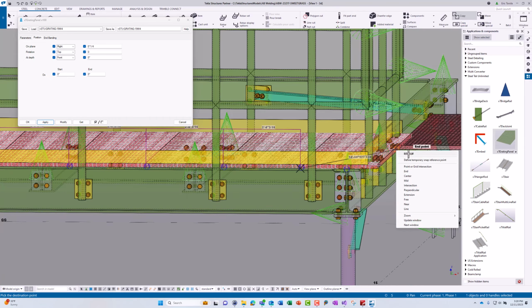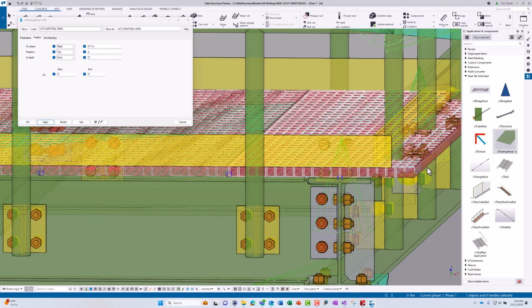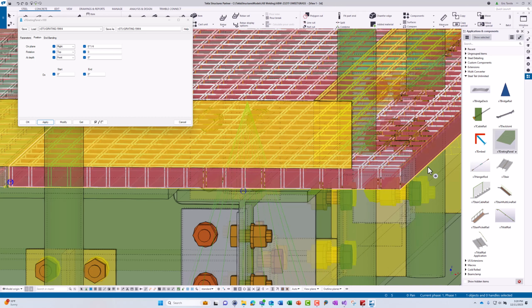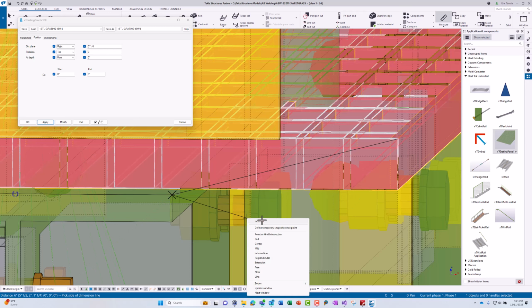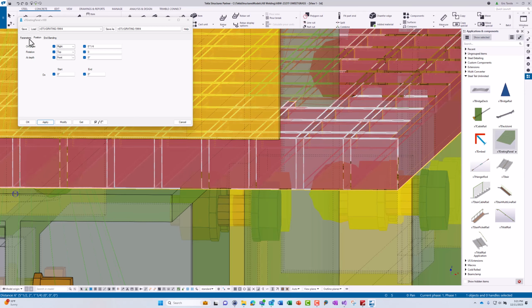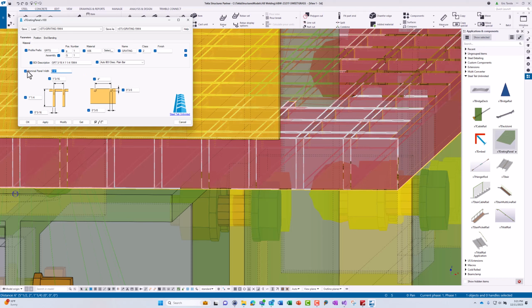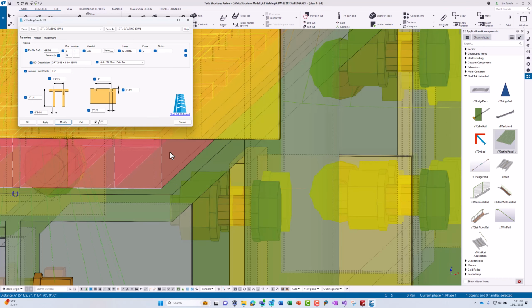When we get to the other end, we will see that the last panel is a little bit wide and it sticks out underneath the railing. Now we can easily measure the number of bearing bars back we need to go for the width that we need on the last panel and adjust it accordingly. On the measurement, it looks like we should remove about 6 inches from this 24-inch panel width, which would make it a nominal width of 18 inches.